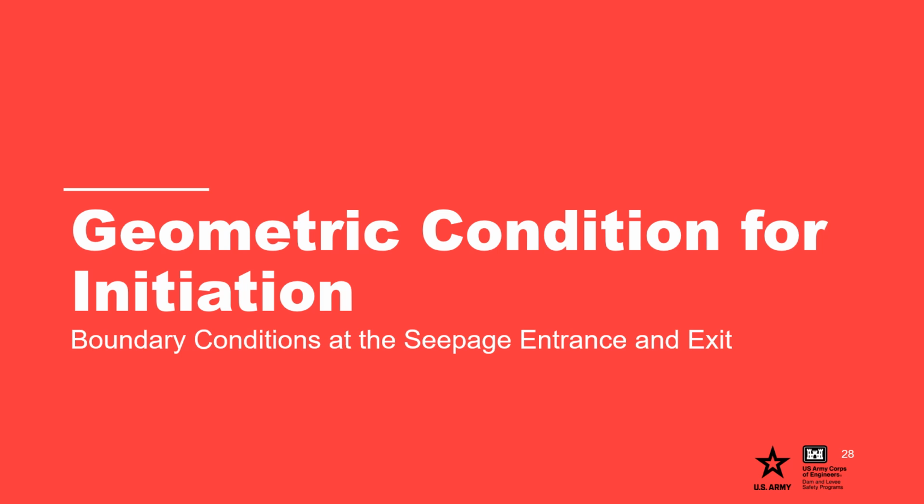Geometric condition for initiation: boundary conditions at the seepage entrance and exit. Assessing the seepage path length requires an understanding of the upstream or water side and downstream or land side boundary conditions. The next set of slides will examine potential seepage entrance and exit locations.